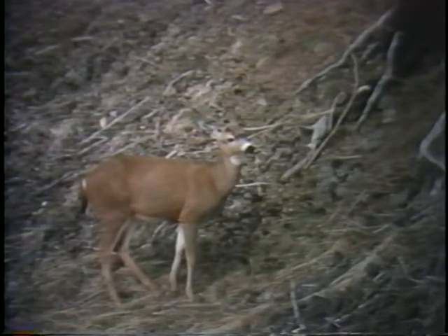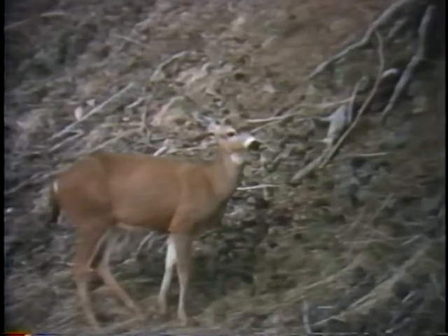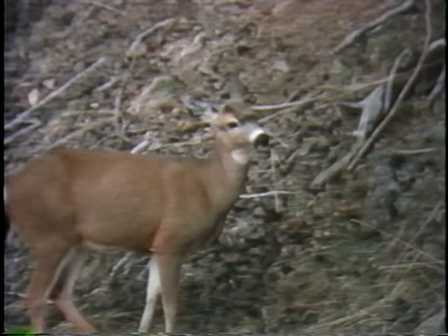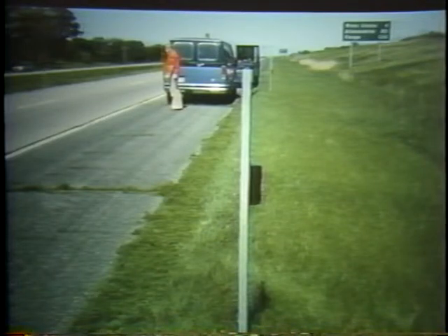Another special situation is created in many parts of the country by wildlife crossing the highway. Fencing doesn't usually prevent deer from crossing roads, so other means must be used. The special delineator used in these areas redirects the approaching headlights transversely away from the roadway. An illusion of motion is created that frightens deer away.